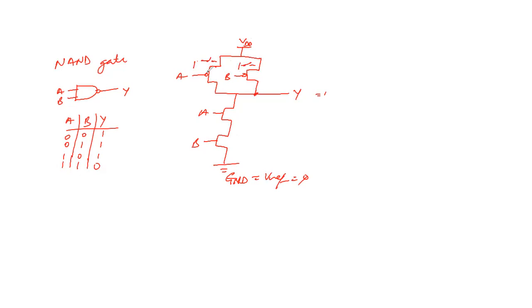Yeah, it's an open circuit when A and B are 1, and this is short. So this is more like a short circuit here. This is a short circuit here. So the voltage at ground potential is seen here, 0 volts, and this is also open voltage because for the P type, this is seen as an open circuit. So this is also seen as 0 volts. So output is 0 volts.